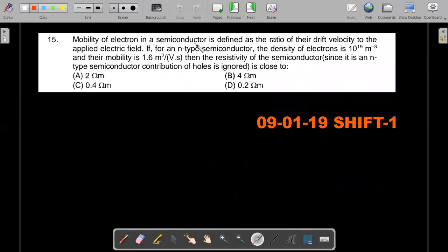Mobility of an electron in a semiconductor is defined as the ratio of the drift velocity to the applied electric field. He need not give this actually, it's there in NCERT. Next time he may not. If for an n-type semiconductor, the density of electrons is 10 power 19 per meter cube and their mobility is given in SI units this way, then the resistivity of the semiconductor, and since she's talking about an n-type semiconductor, you can ignore the number of holes, in terms of the electrons is close to...